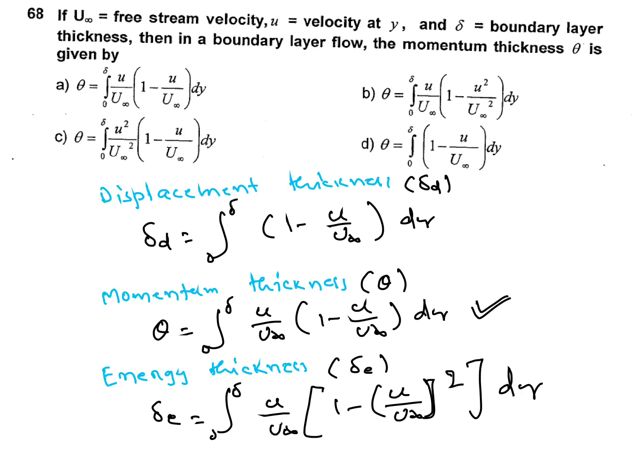In this question momentum thickness is asked, this one, u by u infinity into 1 minus u by u infinity. A is our answer. And this one is for energy thickness, with u by u infinity squared. This one is for displacement thickness.